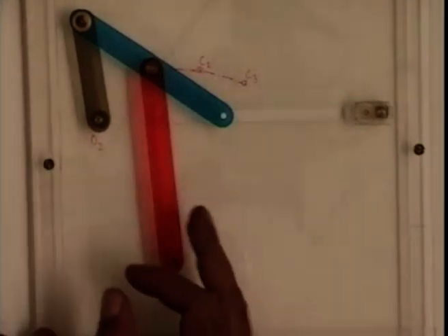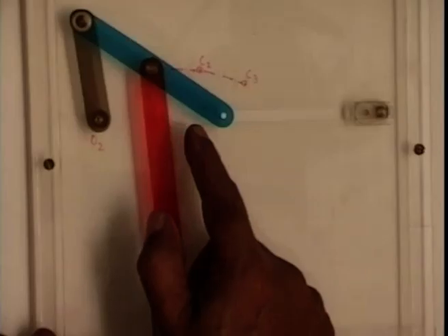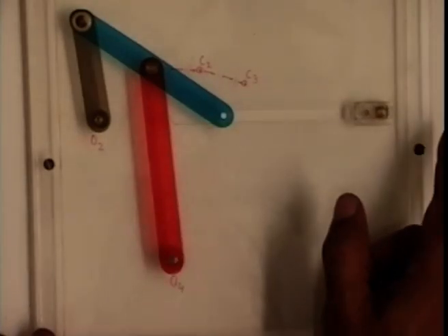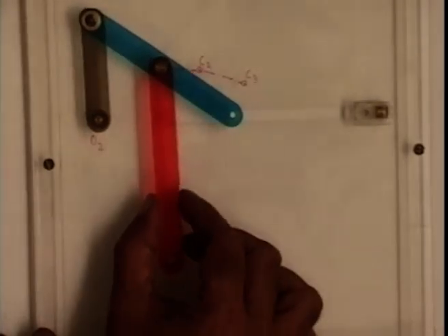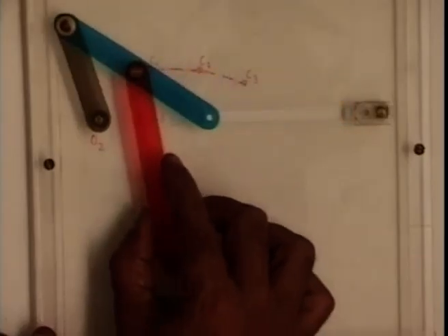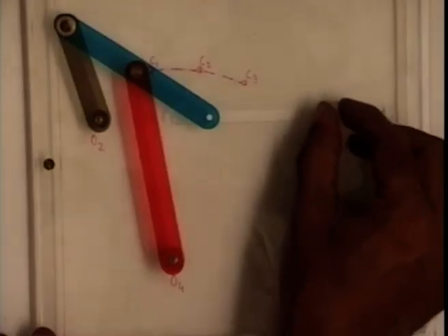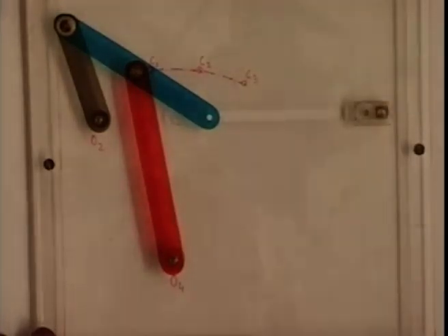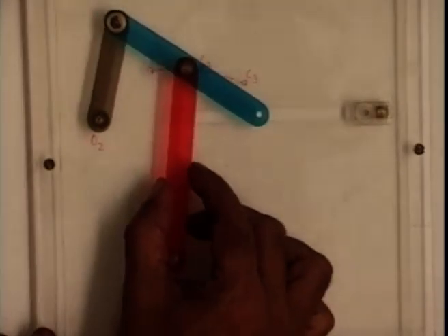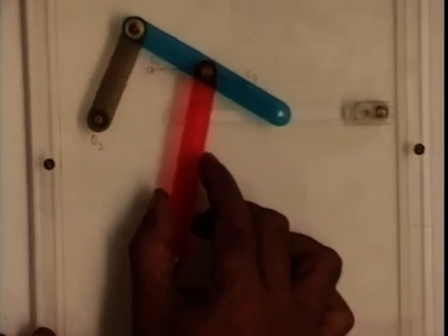Now if we move this linkage, we should see that this point of the coupler is still following the original straight line, but only approximately. We can notice that this coupler point, though not guided by the slider as before, the slider is totally detached, but this 4-bar linkage is also driving this coupler point through the axis of this slot where the previous slider was moving.